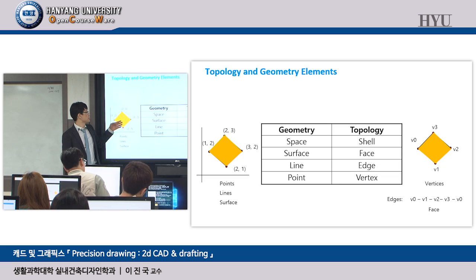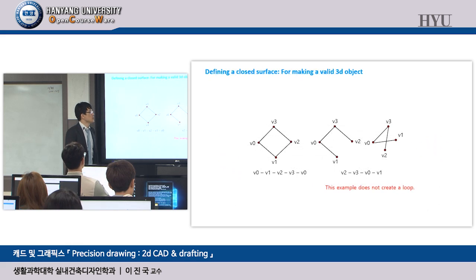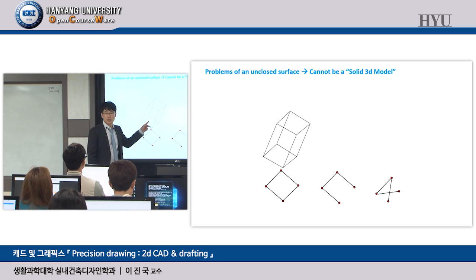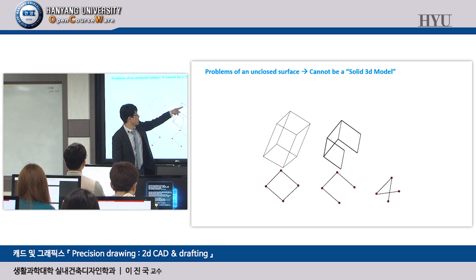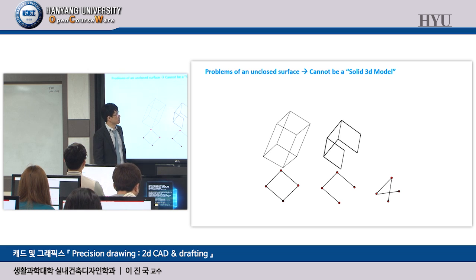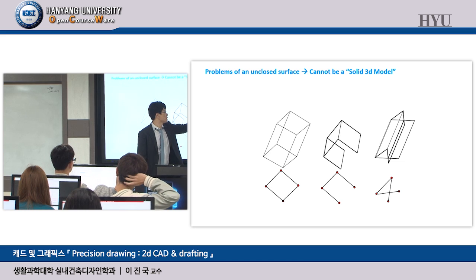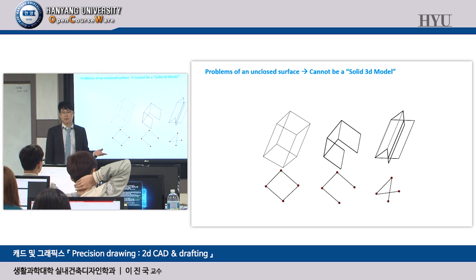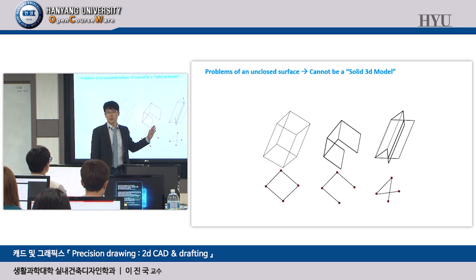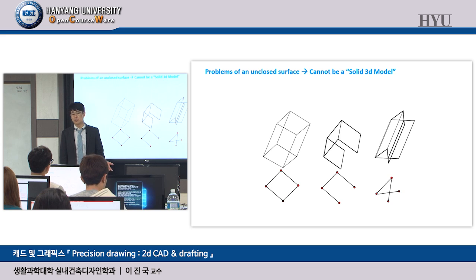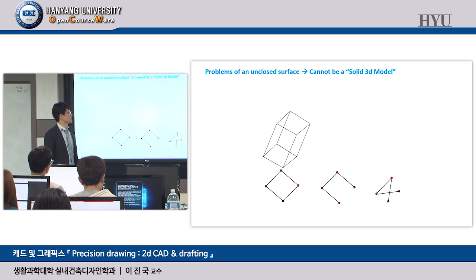How about 3D? So far, this one is 2D, okay? How to create 3D for making a space or shell? Very simple, okay? Take a look. Z direction. This is extrude, okay? Extrusion to create a 3D object. Also, this one is created as a 3D object, but it's not enclosed. That is why this one looks totally different. How about this one? The angled surface object. Those two are ill-defined, so-called surface-based models. In SketchUp, in Rhino, in 3D Max, you can define those unclosed 3D objects as well without any problem because they are surface-based 3D models.